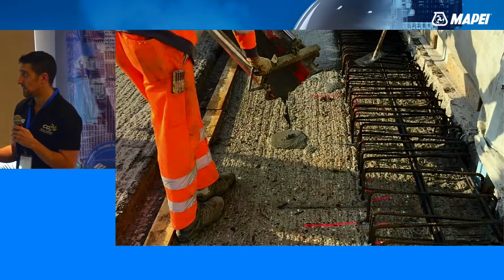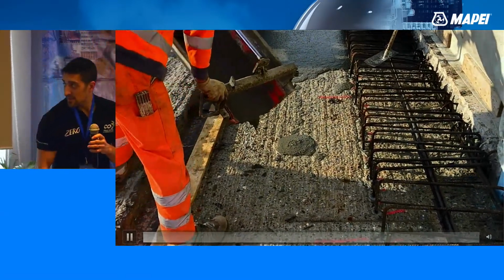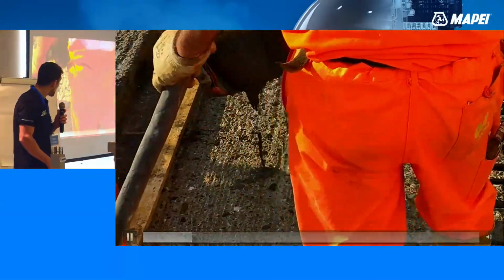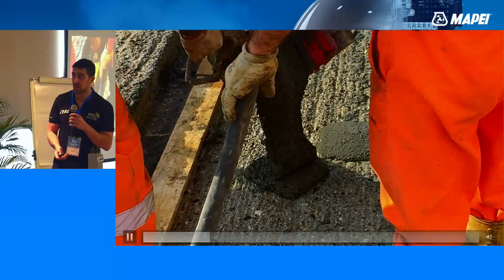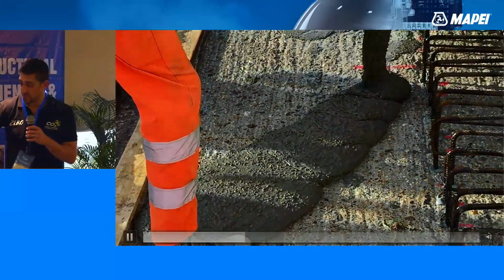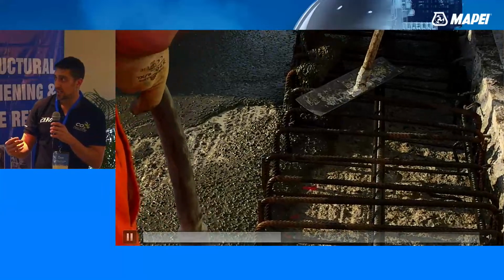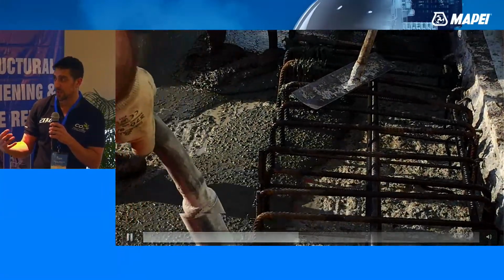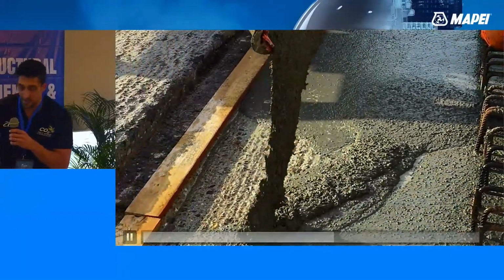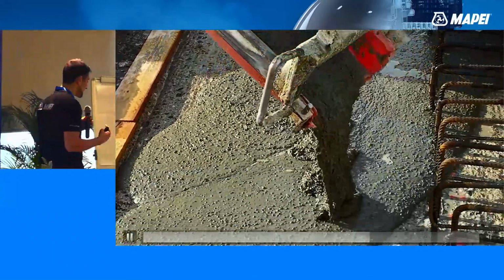The application always in highways. I would like to show you this video. This is one of the products that is called the Planetop HPC Floor 46. So it has gravels of size till 6 mm inside. And what I would like to say here is pay attention at the worker in the top that he is using the trowel for pushing the machine in order that you can appreciate the fluidity, the viscosity of the product. Because it seems to have difficulties even if it seems fluid. In reality, it has a viscosity really particular.